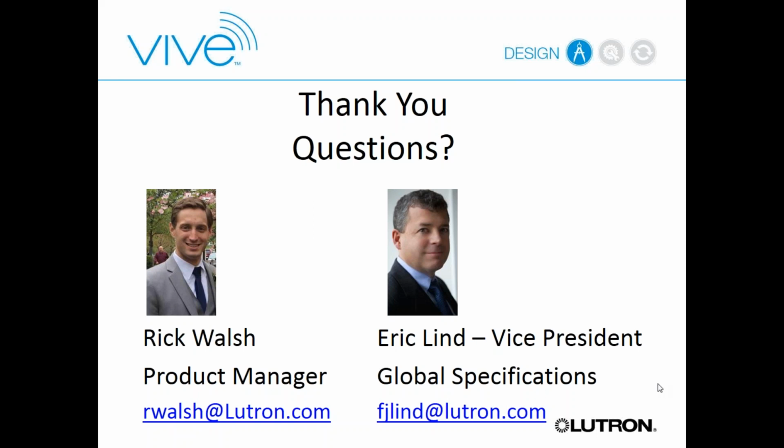Some other questions. Can we create scenes for individual meeting rooms, and how can we interface to other systems? So you absolutely can create scenes. So using one of those Pico wireless remotes, we've got a version that does scene control. In fact, when I showed you that Designer Plus layout, the one that we were showing is a 4-button Pico wireless remote. What that does is you can set presets that send the lights to that scene as you go forward with that. And again, we talked about the integration. The primary method of integration today is through BACnet with the Vive wireless hub, as well as we have contact closure type of components for that level of integration.